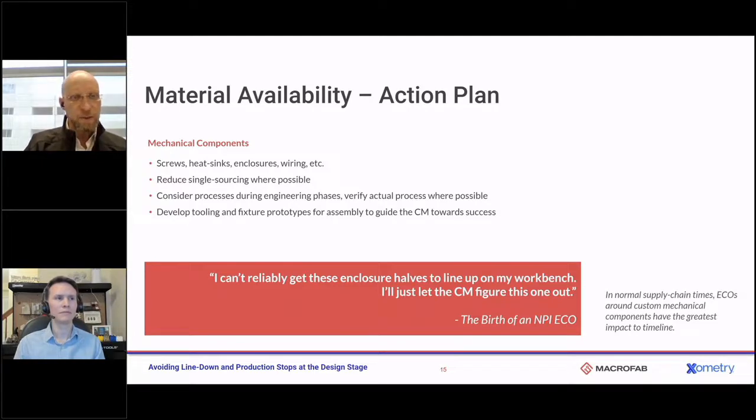And one of the things we talked about, the tooling and fixture issues, that could be an issue during our NPI phase. Well, consider building those and starting to build prototypes of the tooling and fixtures you're going to use during the design phase, right? Because you don't want to get to the point where you think everything's going to be great. We're going to go ahead and build a fixture, and then the PCB won't fit in it, or one of those pins won't line up. And now we've got to go back and rebuild this whole fixture again.